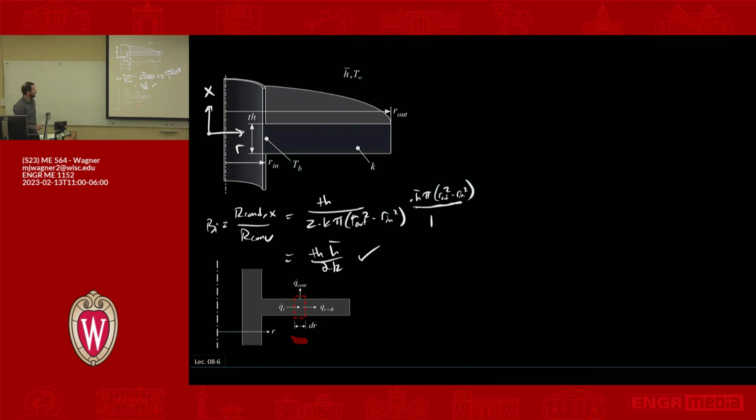We have heat flow coming in the R direction, leaving in the R direction, and then we have convection to the surroundings. Be careful again that, depending on what we assume, we're going to want to probably use the total area here. But we need to be consistent about the area that's exposed for convection. So let's write out expressions here. First, our energy balance is as follows.